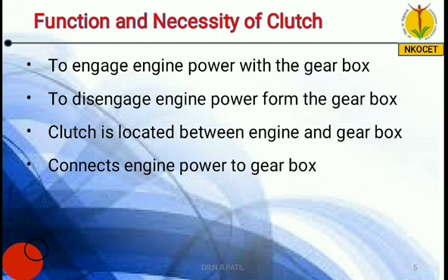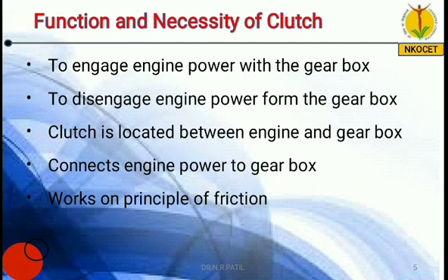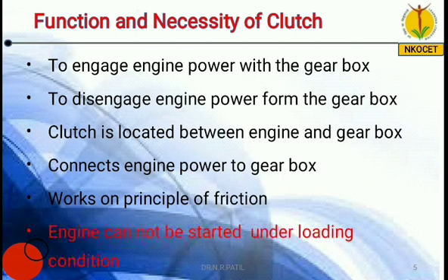Next, it connects engine power to the gearbox. Definitely it is used to connect engine power to the gearbox, and it works on the principle of friction. So let's see. Engine cannot be started under loading condition, and this is the reason why we need clutch. Why we need clutch?